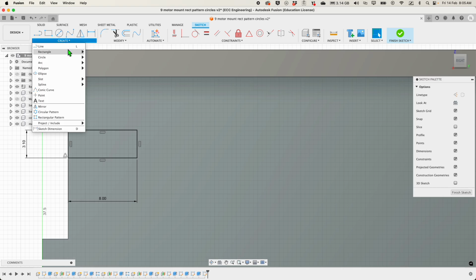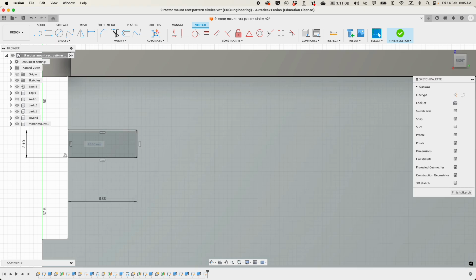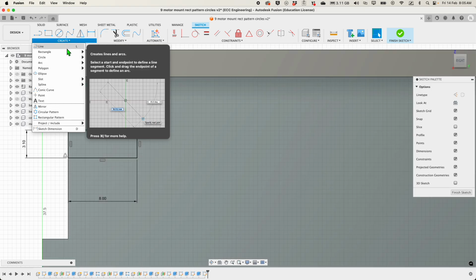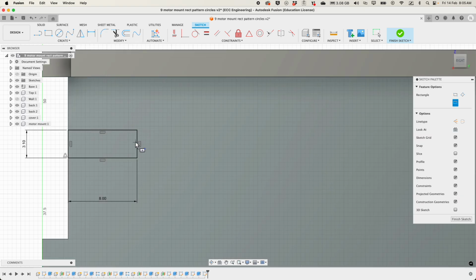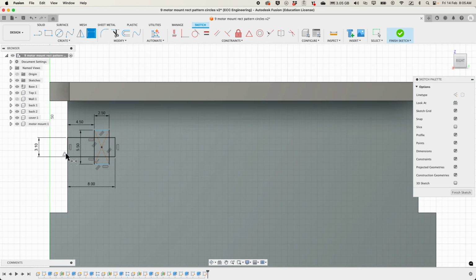We're now going to create a rectangle, center rectangle. I'm going a little bit faster now because we have done this before. Oops, I clicked it, so I don't want to do that. Create rectangle, center rectangle. Again, find the center, but don't click it. Slide down, and it's holding that line for you. And that's going to be 5.5, tab 2.5, enter. And we're going to dimension from there to this bottom edge, and that should be a 4.5. Okay, done with one of those.